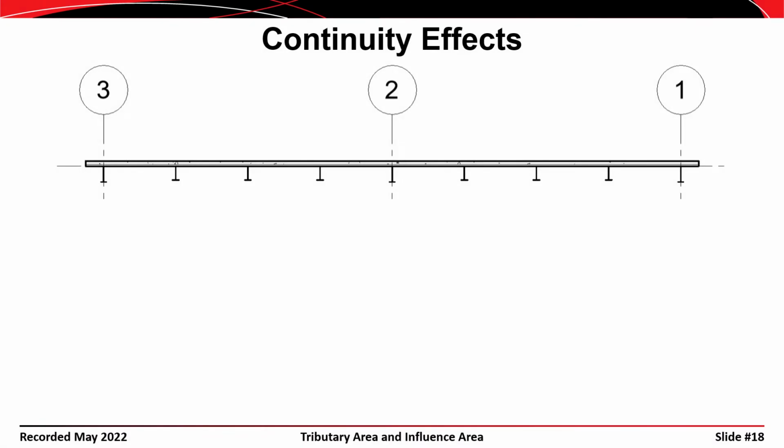So this is a cross section of the building. I've worked with Revit to make this so you can see the concrete is represented there, and you can see each of the floor beam members cut in section. When we cast the concrete, it's usually cast in one continuous pour, plus there's often a metal deck in place. If it's a reinforced concrete building, then the deck would probably be formed up with plywood or something like that. But in any case, the concrete deck is going to be continuous across the members.